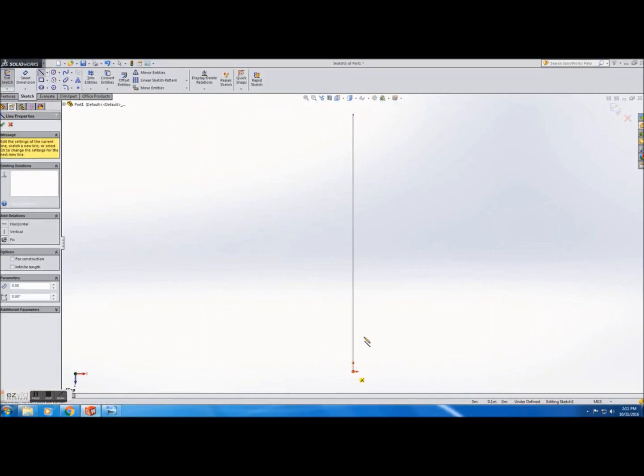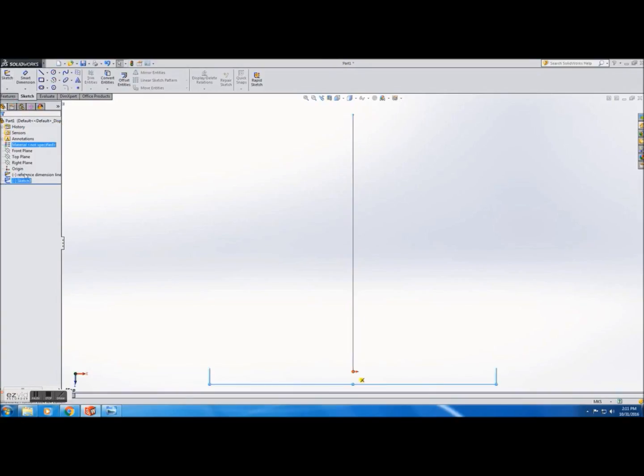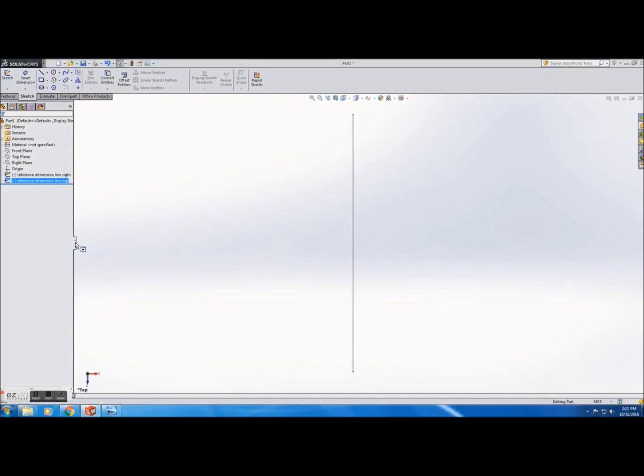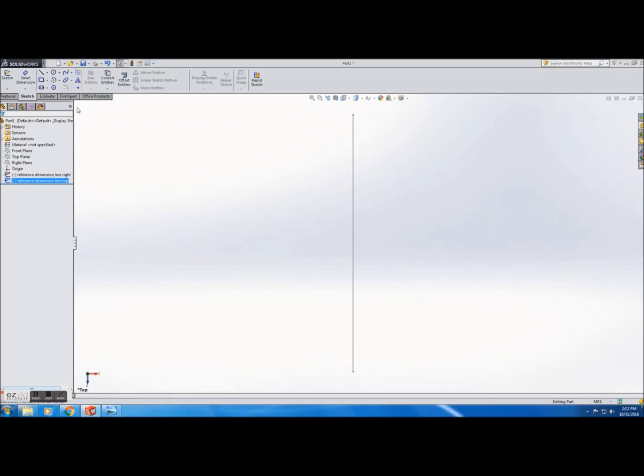So I'm just going to go ahead and draw another line in the other planes that we're going to be working with that matches up with the length of the original line that I've drawn. This is simply because of the way that SolidWorks works: it doesn't always let you align things on different planes if you're going at it from a weird angle, so just make sure that you've got lines on every plane. You'll see what I mean if you try to manipulate a certain sketch from an angle that is more than 45 degrees from the intended observation angle, normal to it.